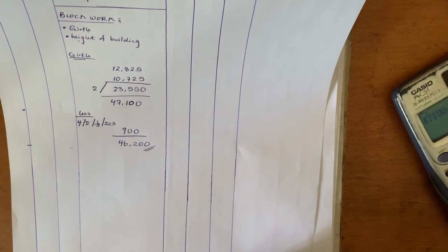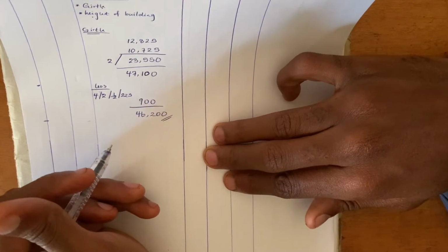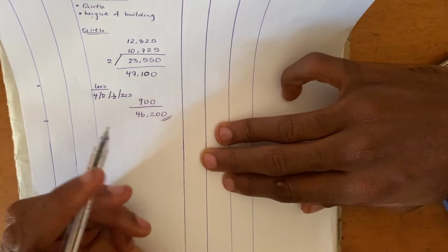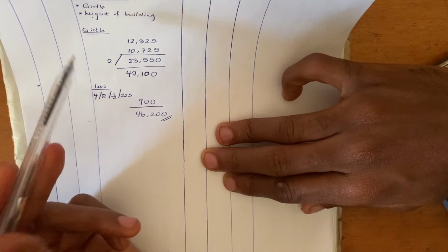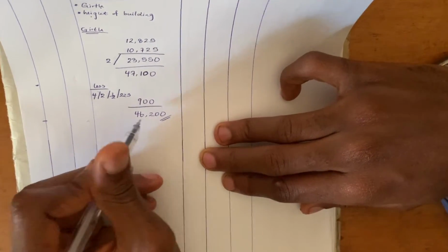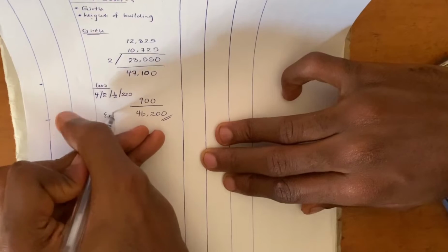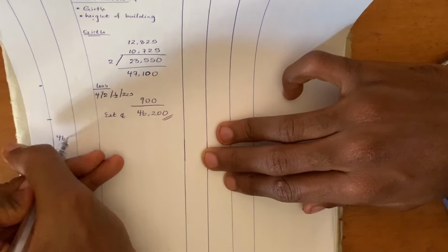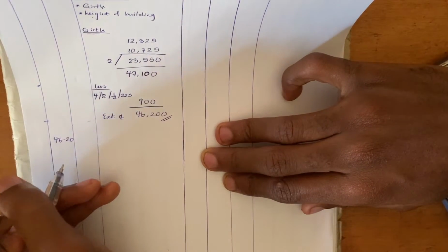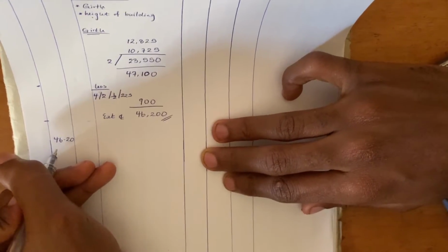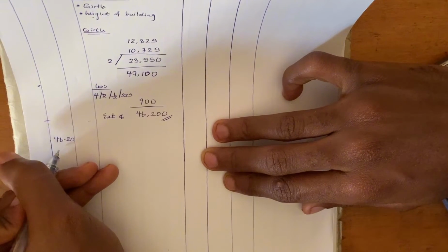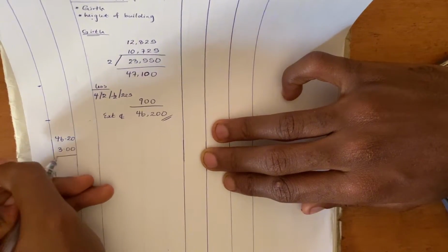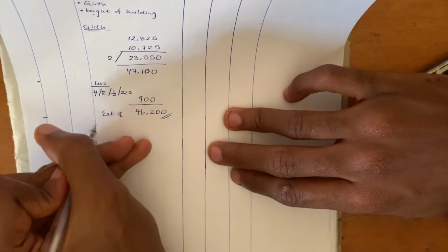Then we will book. We know that the height of our building, as assumed, is 3,000 mm, and I said that the measurements we're going to be needing are the girth and the height of the building. So our external girth, that's the external center line, will give me 46.20 when you convert it to meters, and the height of the building is 3,000 mm. So you convert it to meters, it will give me 3.00, and then you close. Then we describe.